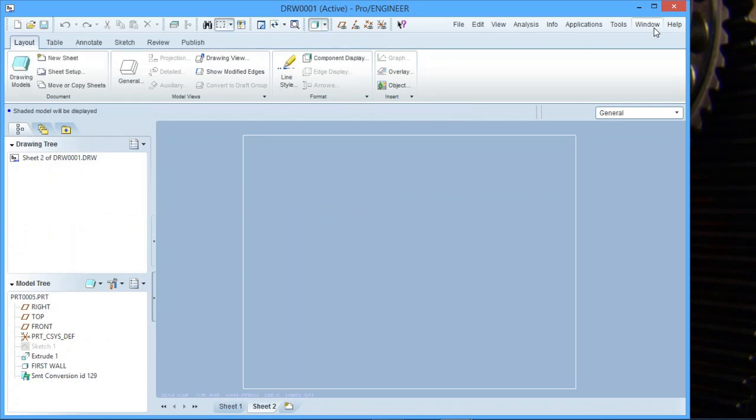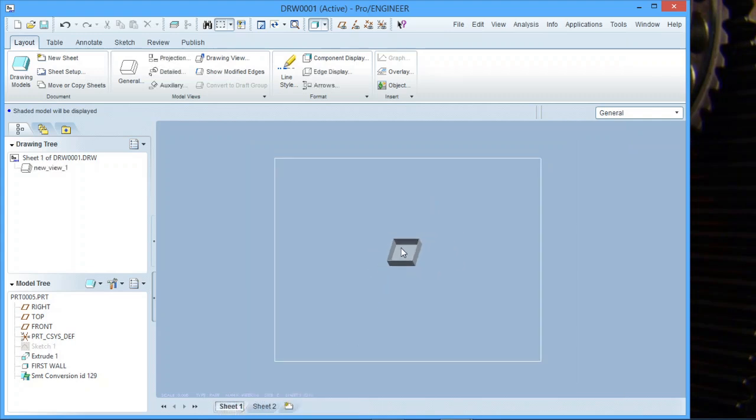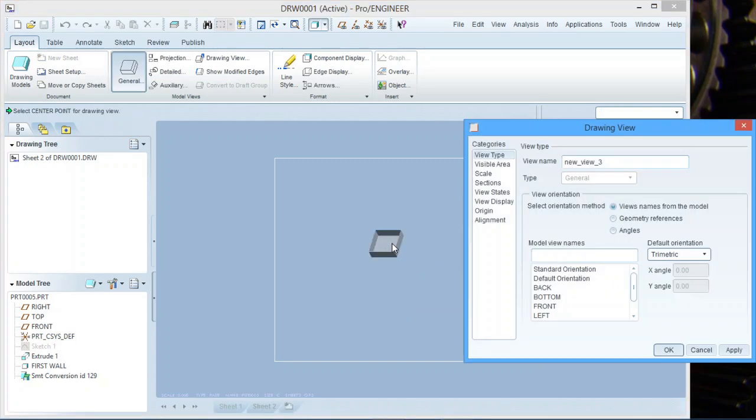Okay, so now that we've got this one, I'm just going to close this. We go back to our drawing. Now I've got the fully formed one here on page 1. Now I want the flat state, so I can indicate the pens. So all I do is I right click, insert geometry, and I click.